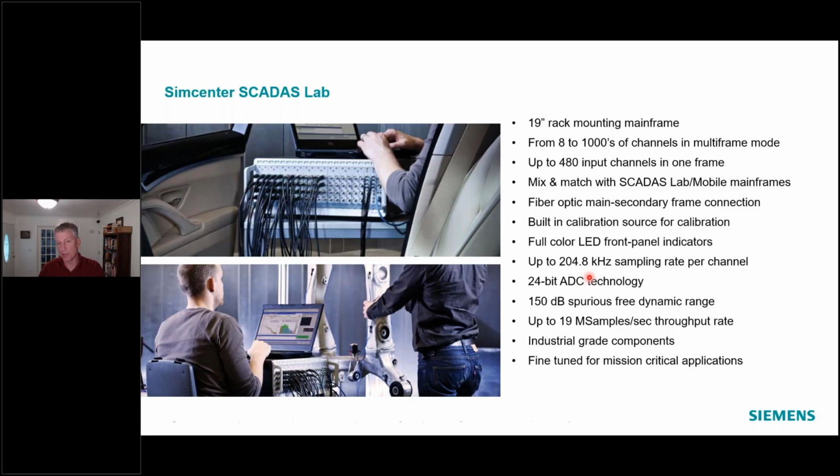Changing the number of channels being measured does not scale that up or down. It's really down to the hardware level itself as to what that input module can measure. And you'll see some details later on where some are 204.8 kilohertz, some are 51.2, etc. But that's one thing to keep in the back of your mind.